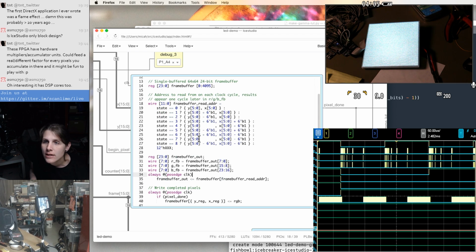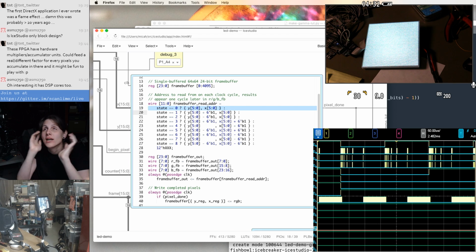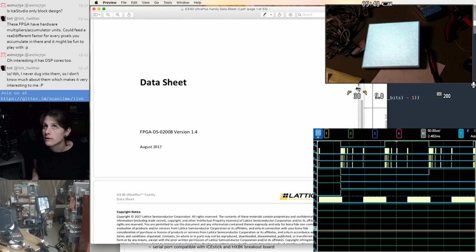Oh, right, because this is 9 now, and we're only dividing by 8. I could add a subtraction, I could multiply by... I mean, we have multiply and accumulate. I could just do it multiply. We haven't really had a lot of really great use cases for multipliers, but two things would be great for here are any kind of brightness scaling, or alpha blending, that kind of thing, or for generating coordinates for any kind of linear transformation.